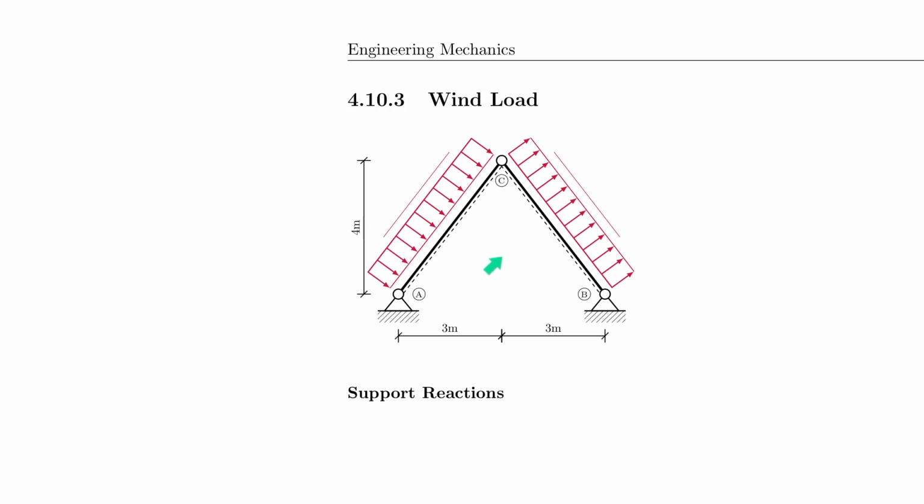And so this is not a symmetric system anymore. It's a little bit more challenging, but also a little bit easier because now all your forces are 100% perpendicular to the axis of the beam. So there's no parallel component in this case. That should make life a little bit easier. Wind, similar to snow loads, is defined per geographic region.